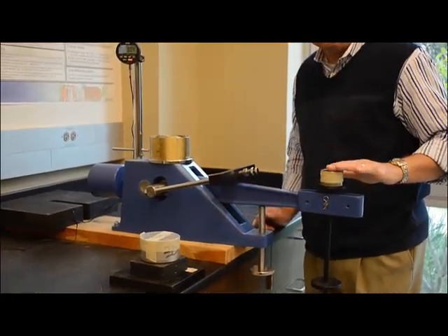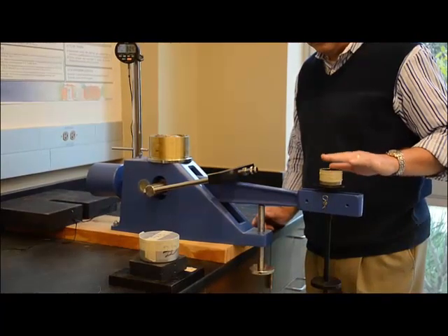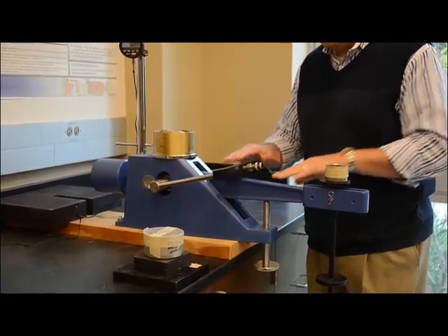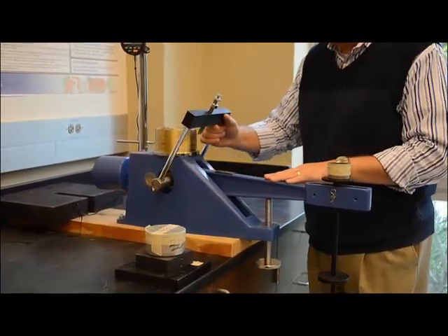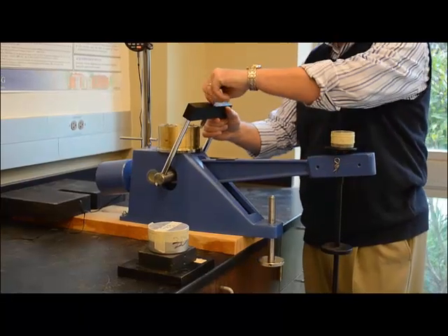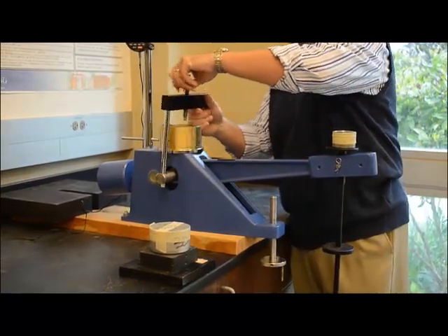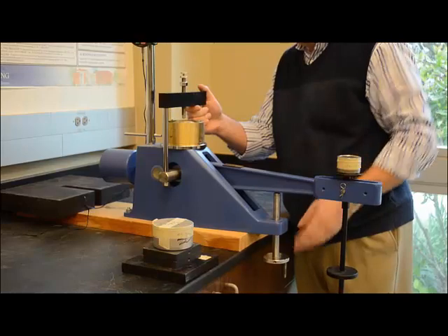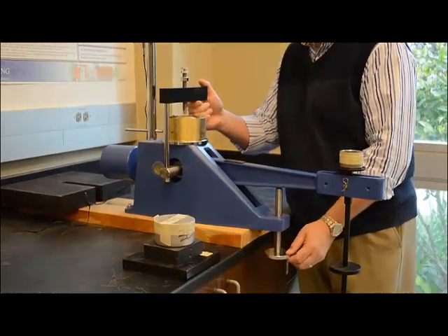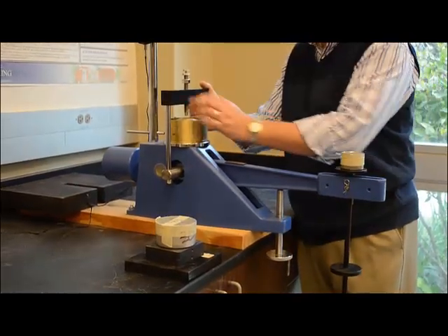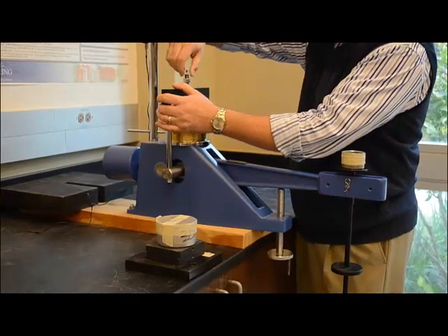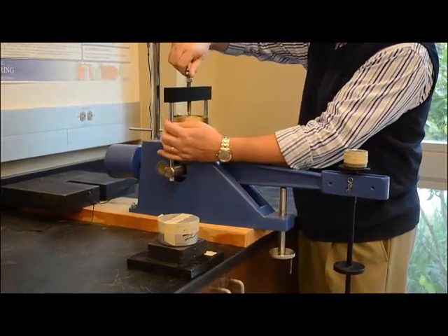That's a very small tin with not a lot of weight on it, just to keep everything in place while we put the initial water to saturate the soil sample. So you'll see we need to adjust that crosshead appropriately. Notice it's resting on a loading jack, which I just screwed up, and I'm going to thread that cross beam